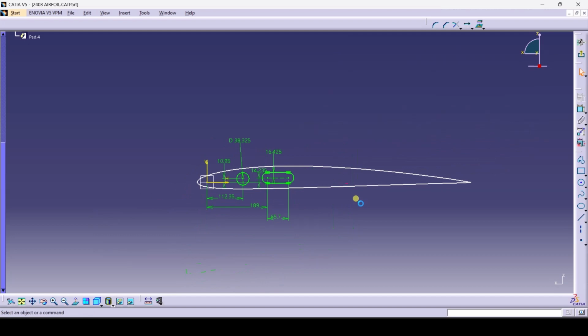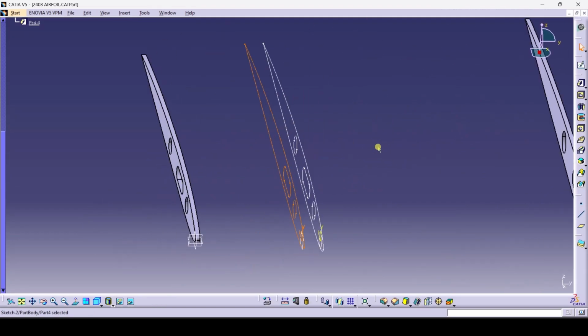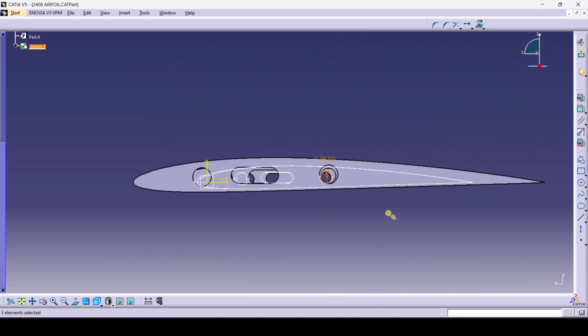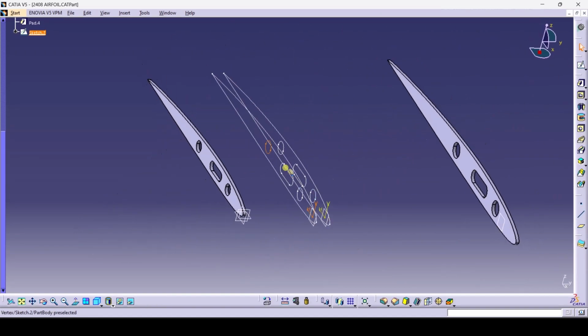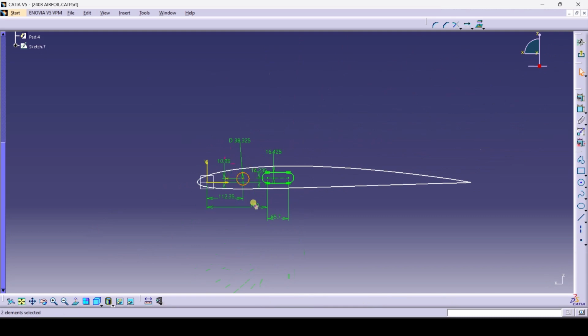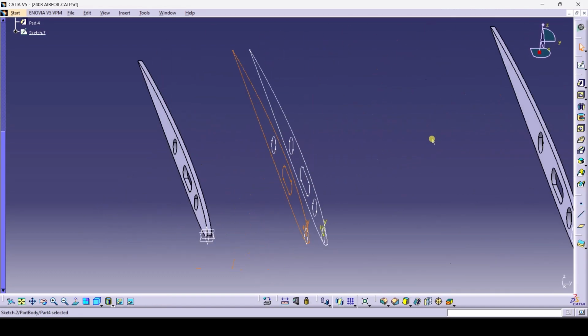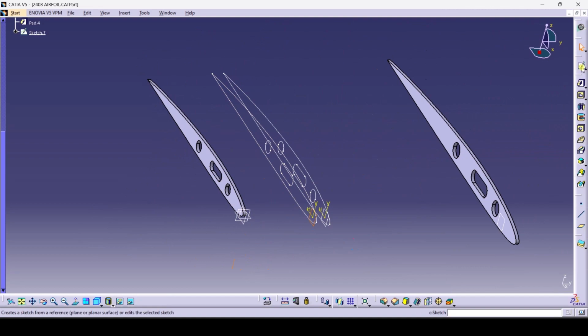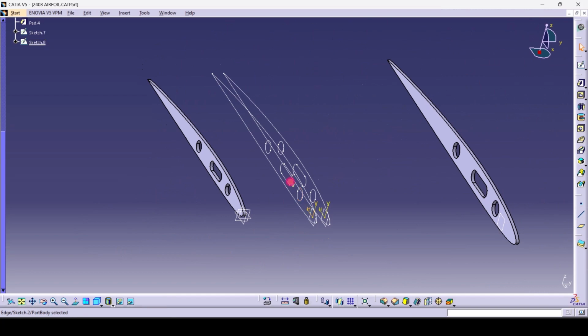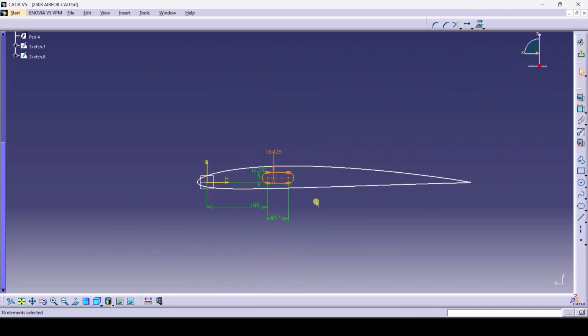So how we have to do it, for example, this profile I am taking, first this circle I just cut, then you can take the same plane, go to sketch and just paste it. Okay, now the circle is in a different plane, and in the same plane itself we can create an infinite number of planes over and above. Then now this circle I am removing, just cut, select the same plane, go to sketch, then paste.